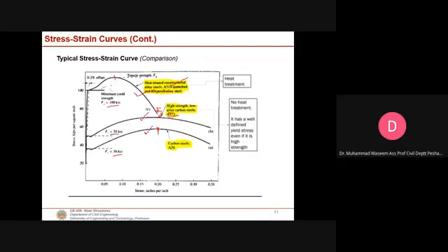The increase in strength in the high alloy steel is due to the different components used in the steel alloy other than carbon and iron. They increase the strength of this material, but at the same time they reduce the ductility or the elongation in the material, so you will not have a ductile failure if you use this material.